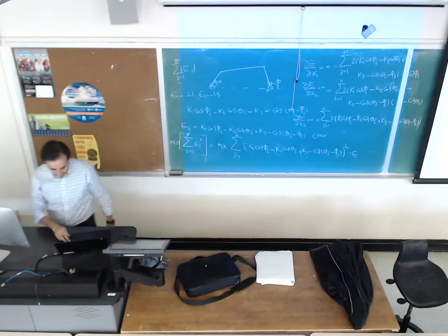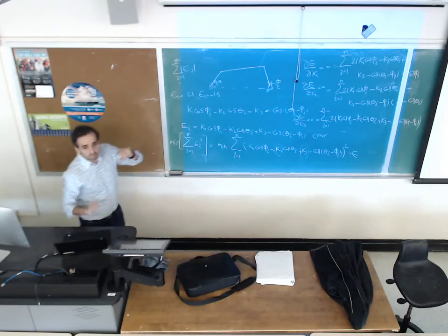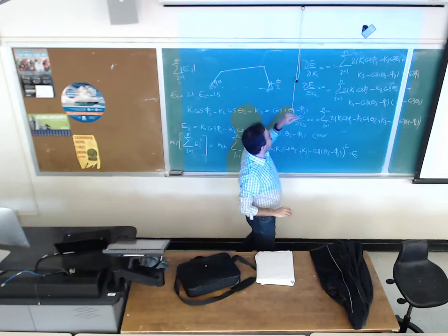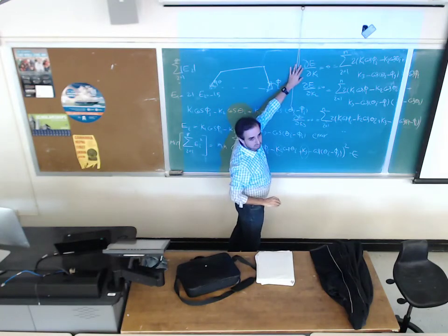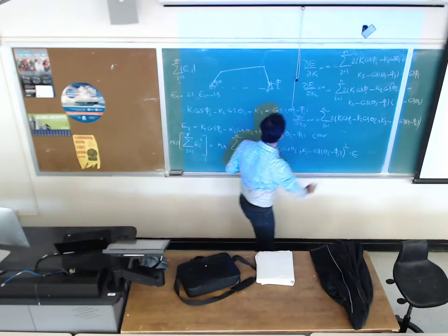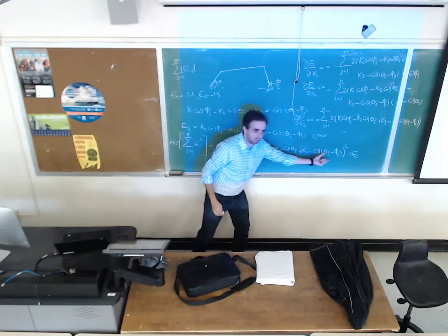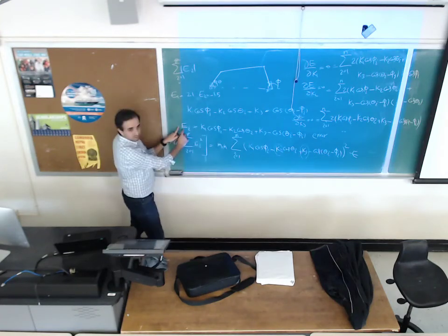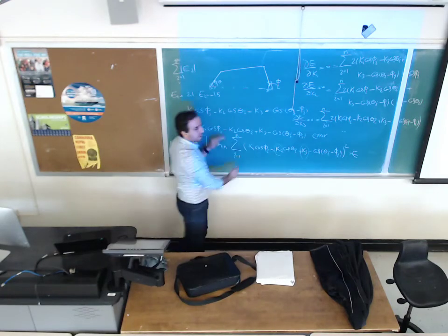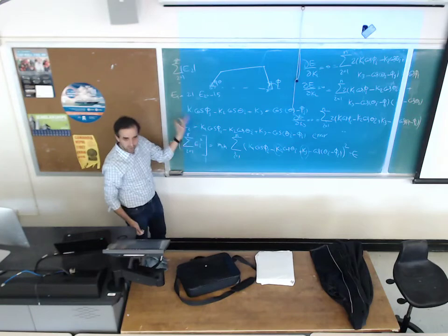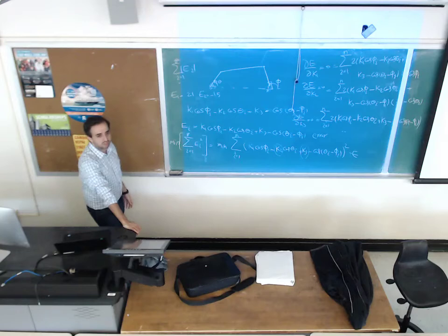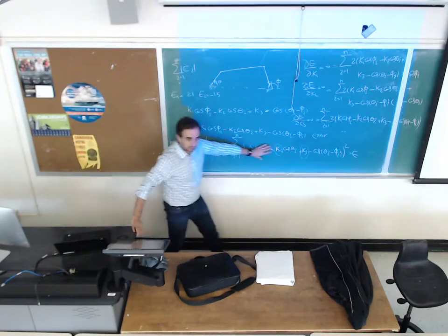Any question on this? Good? So this equation goes with the function for minimizing the error. We are minimizing this function, which is the summation of the squared error. This is the error. I square that, and I add them up at all 8 precision points, or whatever is the number of precision points that you want to generate. And I would like to minimize this summation.